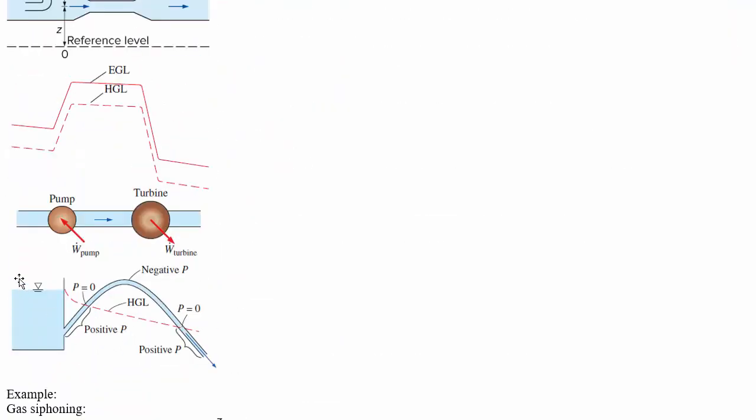as we go down here and then into this part, some of the pressure, the hydrostatic pressure here, gets converted into velocity. If we're at the same depth, then it must be the pressure term that's changing, the pressure head, which is the static pressure head, that's going into the dynamic head to make this thing move, the part that was the P term going into the V term. And then as you move up, Z is increasing, even though velocity is kind of constant along this, so that must be because pressure is decreasing.